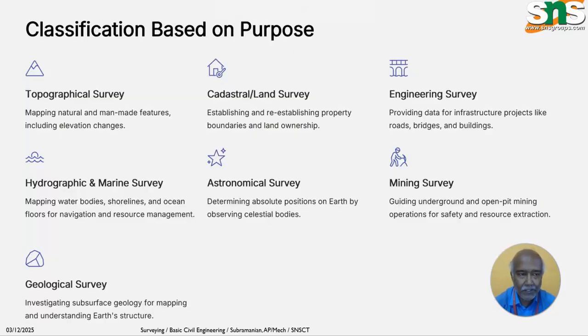And also you see the classification based on the purpose. This is a topographical survey, that is mapping of the natural and man-made features, and also the land survey, whereby we establish the property boundaries, and land ownership is also maintained. And finally, the engineering survey, which provides for infrastructure like roads, bridges and buildings to be provided for the land itself. Is it necessary or not?